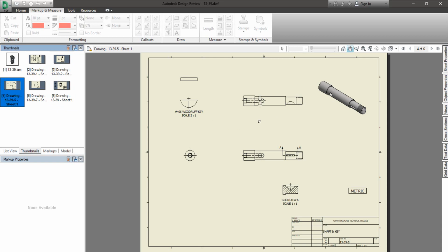Here in this sheet for part number 5, we want a top view showing things, so you can dimension this hole, and we're putting a section in it so that we can see the side view of it there. And mainly, a lot of that is just detail. Sorry, here's our section down here. Here's our section, so you can dimension this keyway slot and refer to the book on how to dimension that.